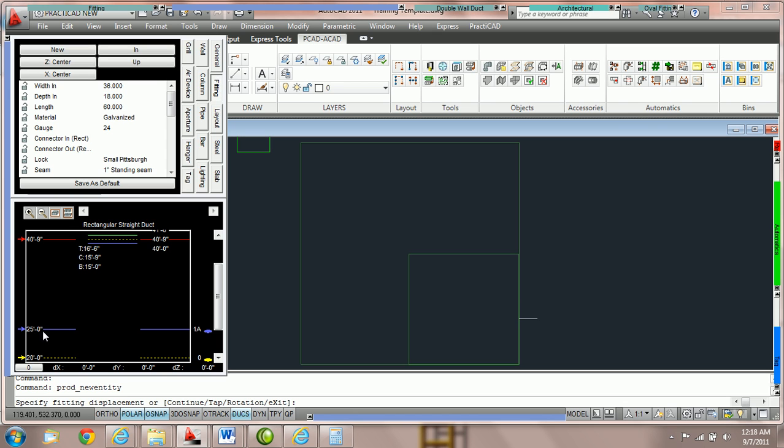So if we've set 25 foot to relative bottom, and we said be 15 foot above it, we're at 40 foot in absolute elevation. So we can toggle between what's relative bottom, and it does not have any effect on our tags, and we're going to show that to you now. So we're going to change the 20 foot back to relative bottom. We come here, we're going to click on our yellow button, and that'll switch it to blue or relative bottom.